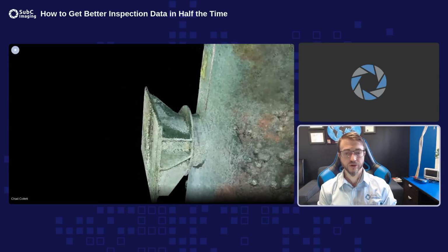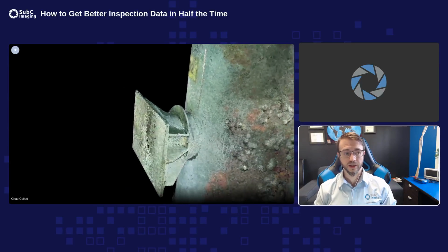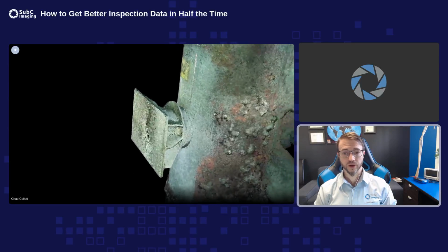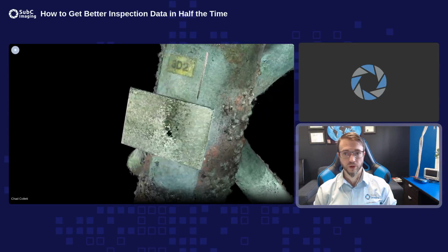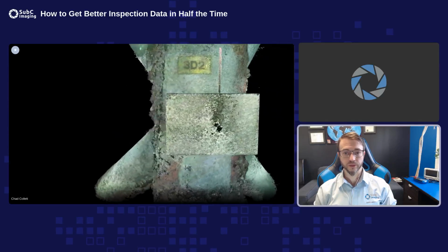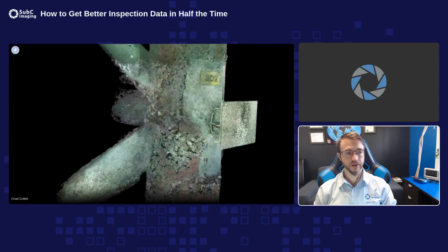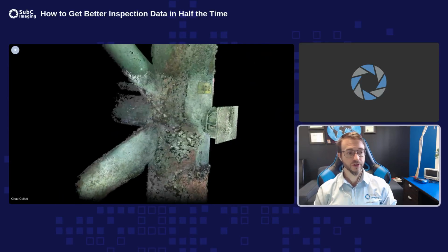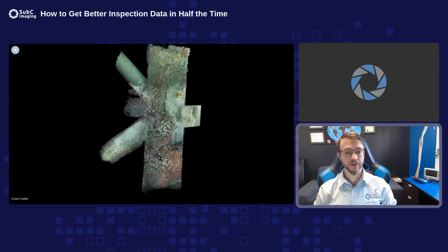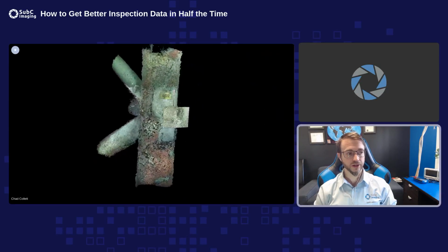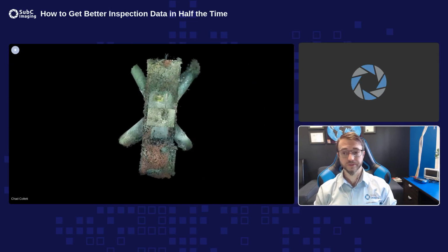This is of an offshore structure. So basically the photos with the camera were taken in a kind of a snake or S pattern on the structure. And then those digital stills were brought back into another software to be processed using a process called photogrammetry. And the digital stills are all 12.3 megapixel, and the sharpness of the images are very high, and it's water corrected. So after it's been calibrated, it can be used to make really high accuracy models.